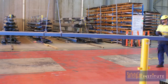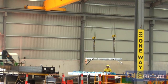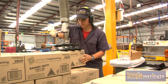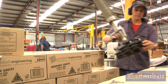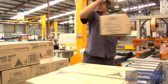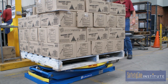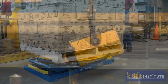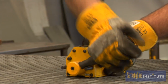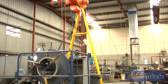An additional design change was to install a dual hoist crane to reduce the need to handle and guide the load. Reducing the force required is a common way of addressing risk factors, for example by using vacuum lifts, gantry hoists and magnet lifts, and providing mechanical aids such as scissor lift tables so that workers can transfer loads at just below waist height. Let's look at some examples which illustrate how good design can help eliminate manual task risk factors.